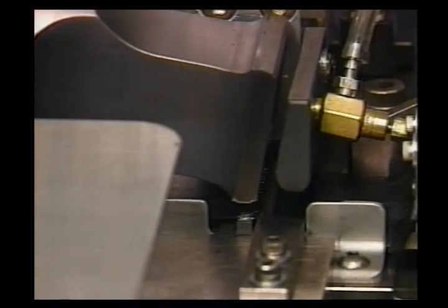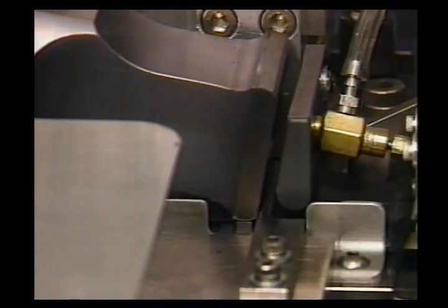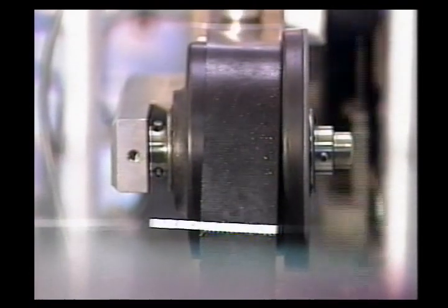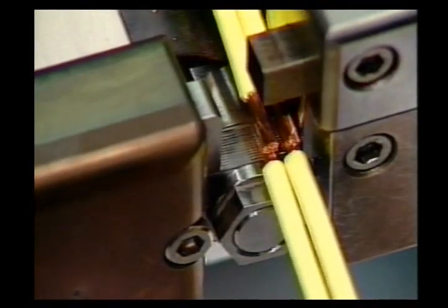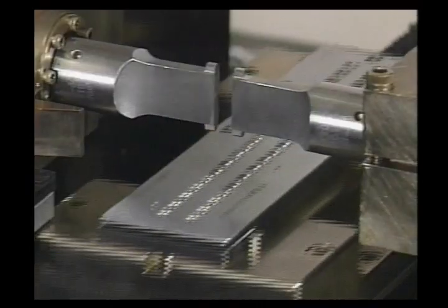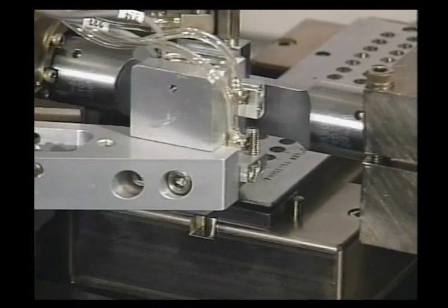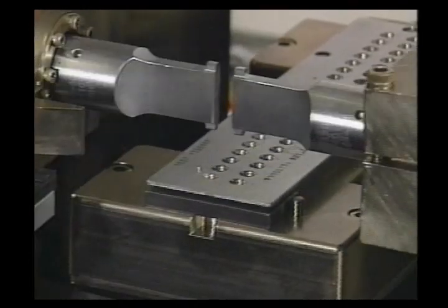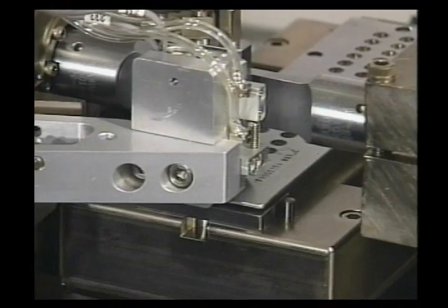Filler metals are not normally required, although they can assist in joining difficult-to-weld dissimilar metals. The electrical and electronics industries are the principal users of ultrasonic welding. Limited applications are also found in the automobile, nuclear, and aerospace industries.